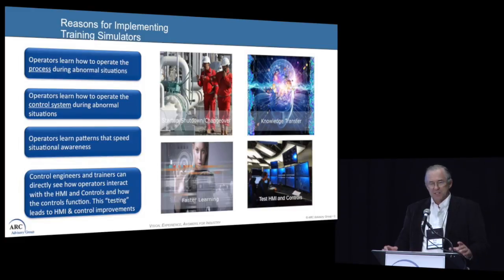There are a lot of different kinds of display devices that the operator might have. He might have a cause and effect diagram showing the number of conditions necessary to start a pump. All of these must be true before the start button will actually start it. He doesn't use that display except at startup. He never even knew where to find it. He has to navigate around the control system: where is that display?